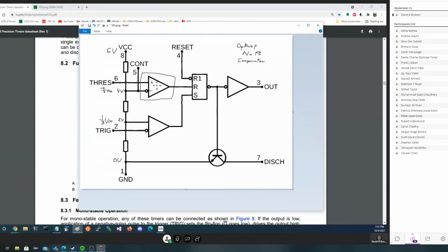And it's comparing, in this case, to see if the plus pin is bigger than the minus pin. Same thing down here. If the plus pin is bigger than the minus pin, this will put full output. It's a comparator. If the top pin is less than the bottom pin, it'll give us a 0 out. So this is a comparator.